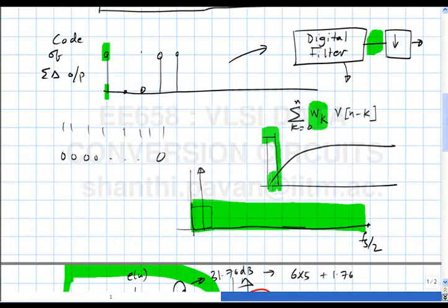But thankfully in today's DSPs, register lengths are not an issue at all. This used to be a problem 10-15 years ago, and everybody and his brother were working on what happens if you take this filter structure and cut its coefficient register number of bits by 2, and then you find that you get 0.2 dB more SNR, and then you have some optimized structure and you write some paper and so on, right. But now hardware is so cheap that you throw 3 more bits, nobody bothers. So unless you're doing some super optimized design, where you want to count every gate, which doesn't happen very often, people don't really bother,